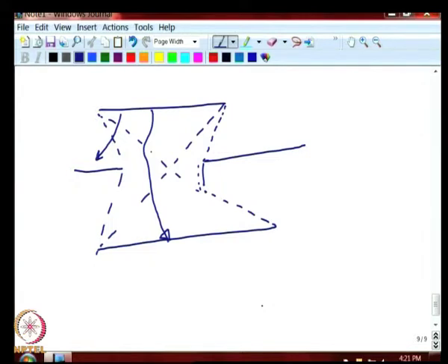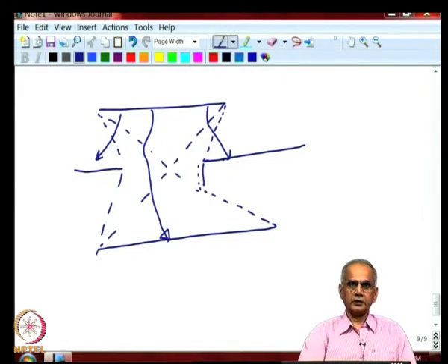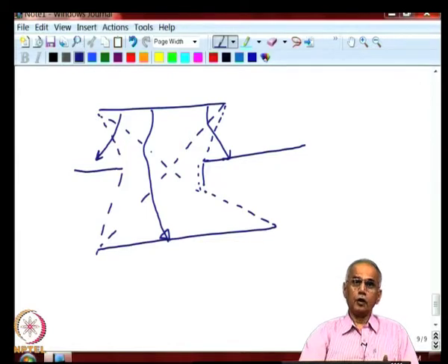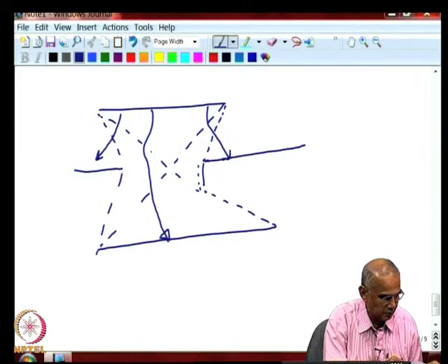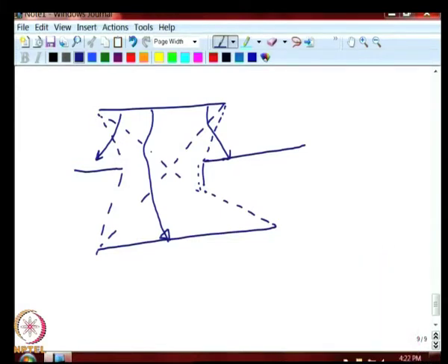So, you can draw various rays and make sure that you have ensured that the construction of the cross and parallel strings is accurate, and that satisfy the rule that any ray leaving surface 1 and reaching surface 2 must cross both the cross strings, and any ray leaving 1 and not reaching 2 must go through the parallel string. So, this is satisfied here, and that should be sufficient to ensure.